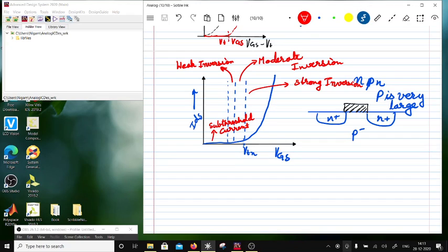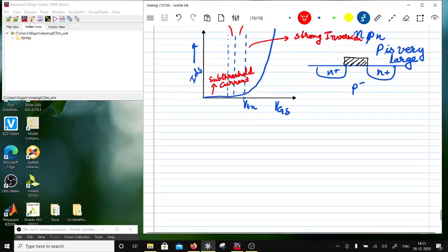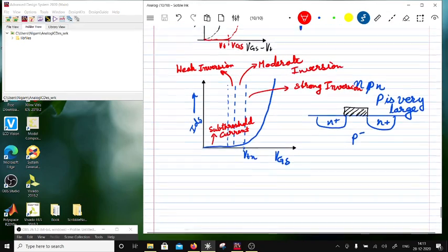So for example, noise consideration will be there, right? So you may take very large devices. You can make a low noise amplifier, operating the devices at very low current densities and very large devices. So usually that happens when you deal with medical or implantable circuits. Okay, so this is the transfer characteristics.